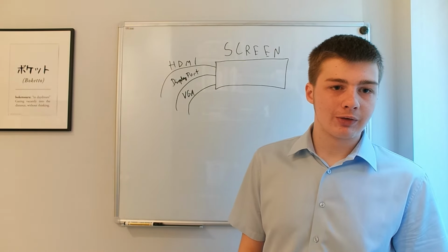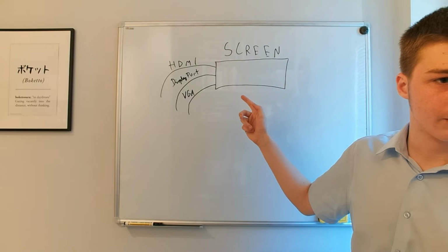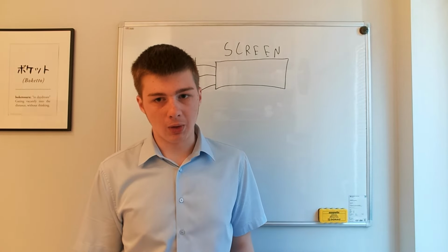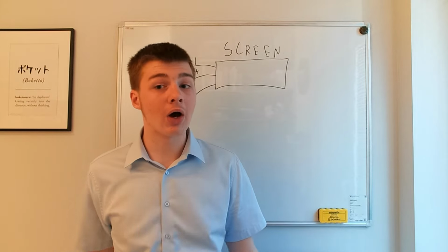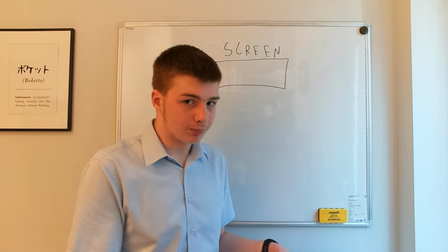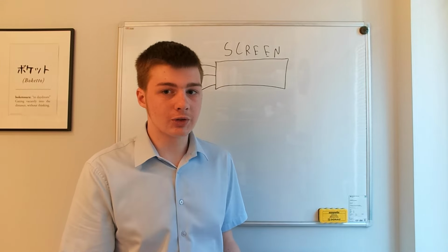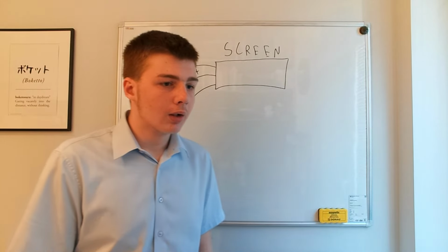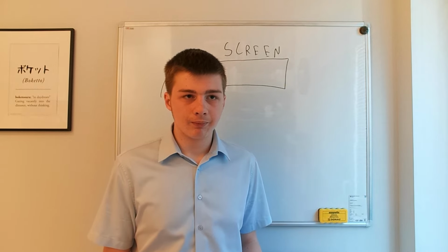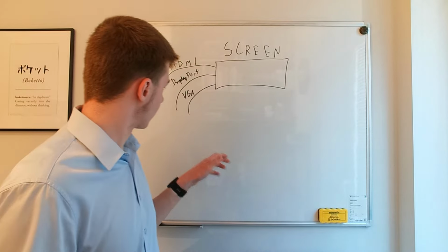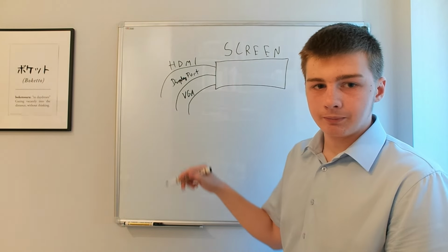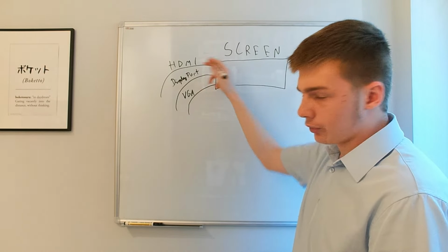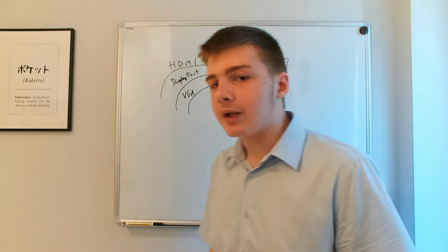Okay, so now we know that we have to send video data, right, which is fundamentally made out of two primary parts. It needs to send the data according to some timings, the video mode. So you need to be sending that data in those timings. This is the video mode, and then you have the actual pixel data. Through VGA, you then send the data about the individual pixels, and it is the same in any other interface. Okay, where do we get this info from, right?